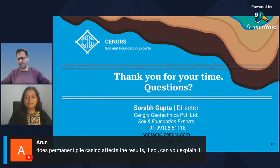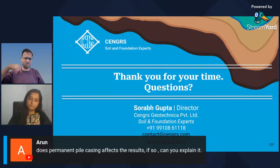I would say it does not affect your results per se. The only effect would be if you have a lined pile, or a liner to a certain depth. Then I would expect to see a uniform pile shaft at least in the lined portion. So a good check is, if you get PIT results and you are seeing variations in the area which is lined, then I might suspect the PIT data and what the data is telling me. Typically in the lined pile, you get a fairly uniform cross section.